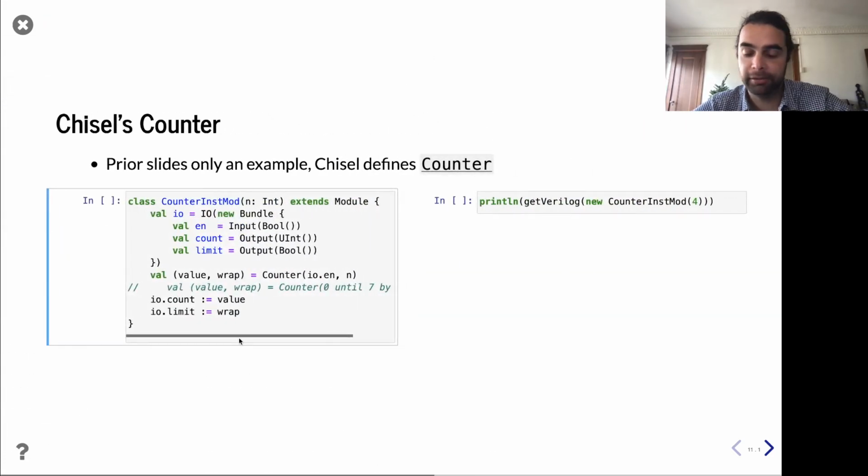Cool. Okay, so like many programming classes, we have students build very basic components over and over again, data structures, whatever. And it's important to remind students that we are reinventing the wheel, right? So you should use standard library components when they exist. So when it comes to this counter, guess what? The Chisel standard library has a counter, and it's actually really great. So you should use that counter. But we still might keep using this counter as an example to understand the internals just because it's simple and easy to explain. But when library components exist, it's a really good practice to use them, right?